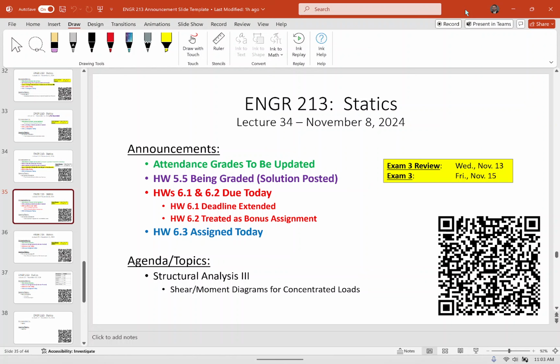And so the response, whether it's being bent or being sheared or what have you, changes along the beam. So for example, if I told you, here's this member, and I said, plot the force inside the member. This would be a pretty boring plot because it would just be 30 kilonewtons. It would just be a constant plot across the entire member. But if I asked you to plot the bending inside this beam, it would not.